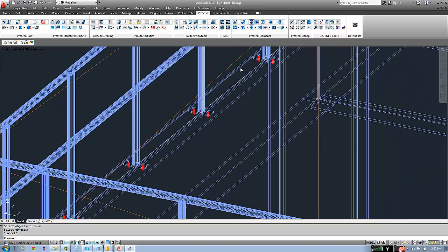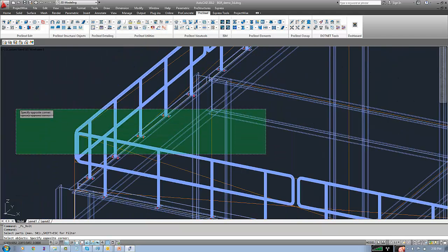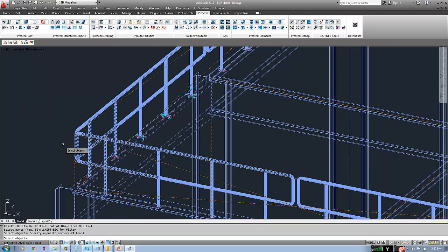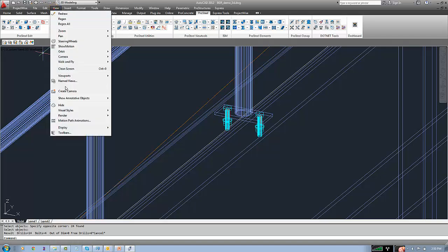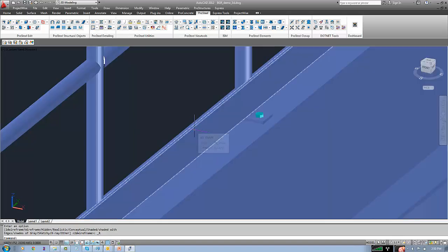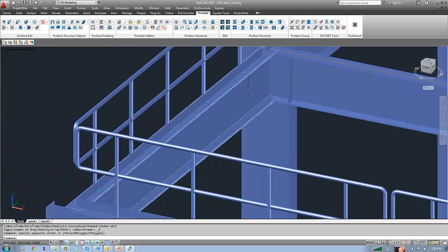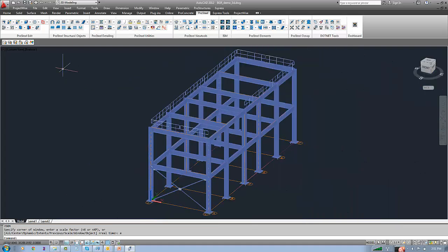Now if you want to assign the bolts, you just go here, bolt all selected parts. I'll just select, and automatically it will place the bolts on the particularly drilled area. For better visualization, let me render the model. Now you can see I have placed all bolts. In the same way you can also create the model at your end, right?